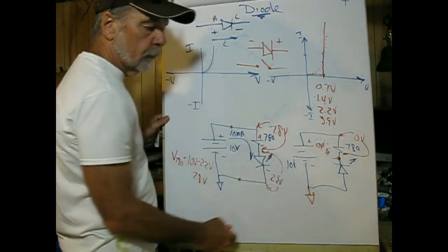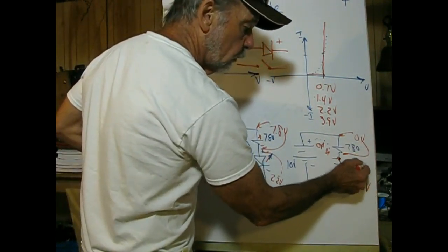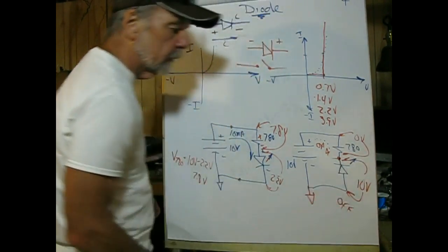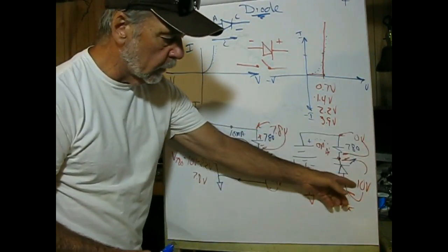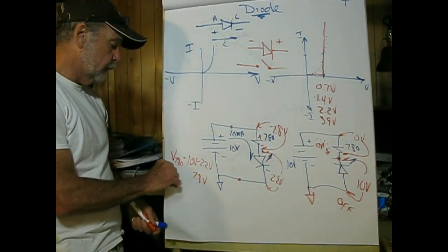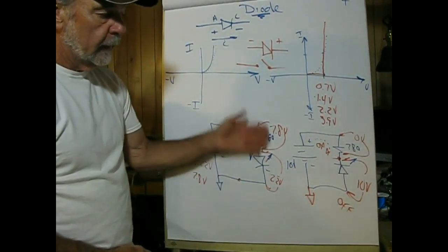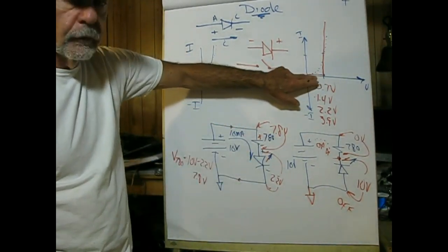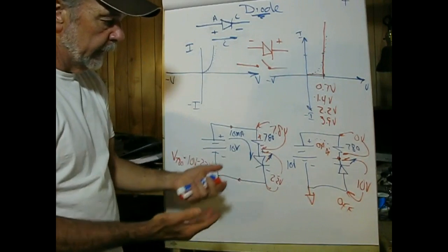So if this is 0 volts, by KVL what we can conclude is that the voltage across the reverse biased diode, that is off, is 10 volts. Kirchhoff's law is preserved because 0 plus 10 is equal to 10 volts. So you have the additional concern of finding out if it's forward biased, and if so, acting upon it, and we won't consider anything in between this. So this is a first level model that we can use to analyze this.